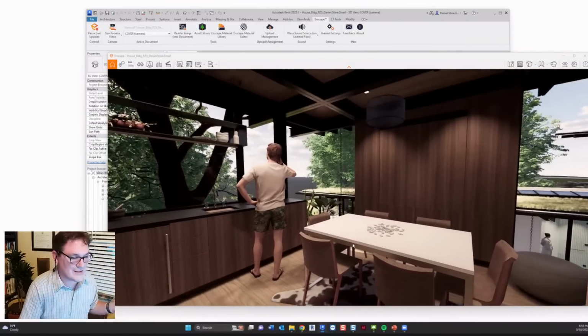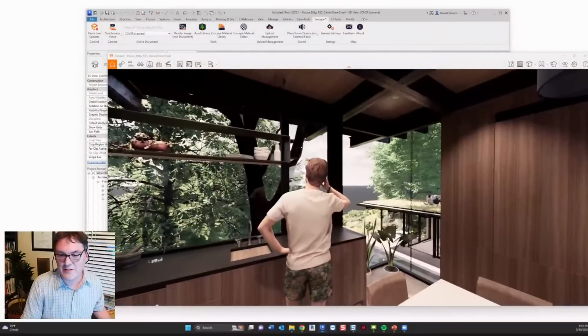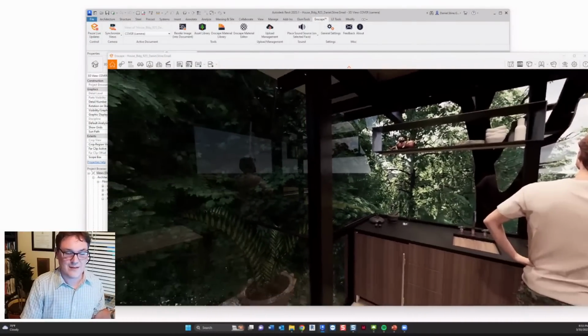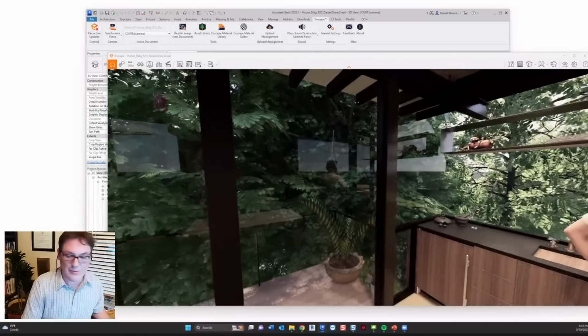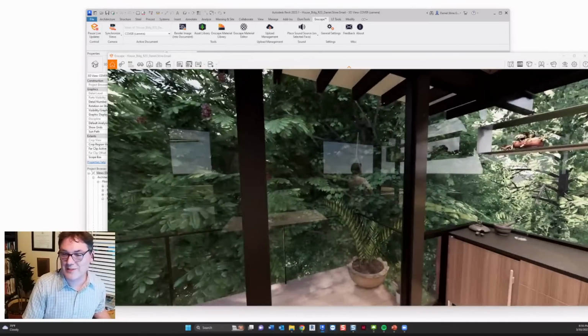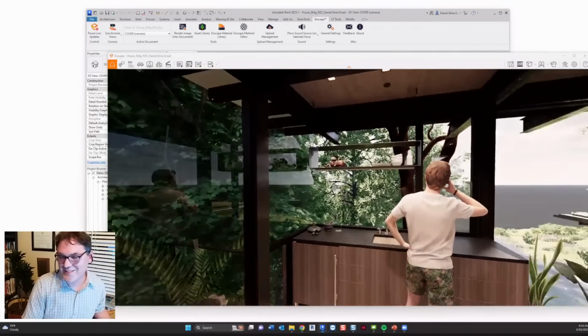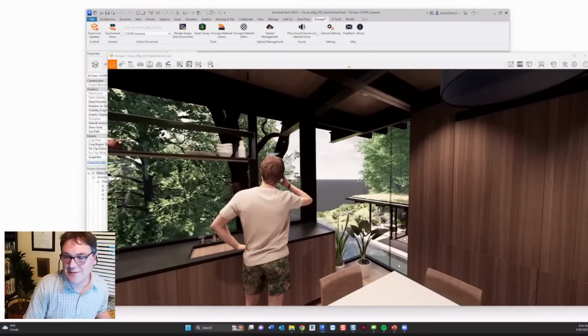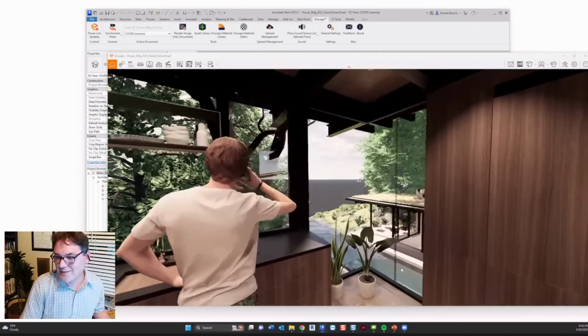When I was at Autodesk's office in Shanghai, China for Inside the Factory, they were telling me that they were helping the design team that was designing the Shanghai Tower. And if you opened up all the worksets on this really high end computer they had, it would take 1 week to open the model. But if you turn off all the worksets except for floor 64, it would open like any 20,000 square foot building.